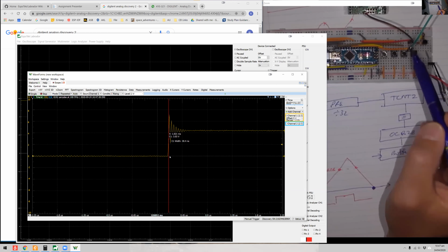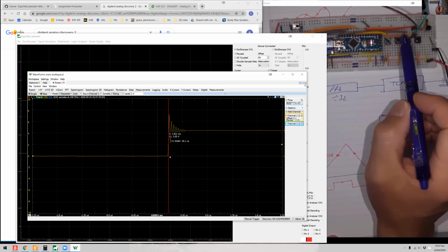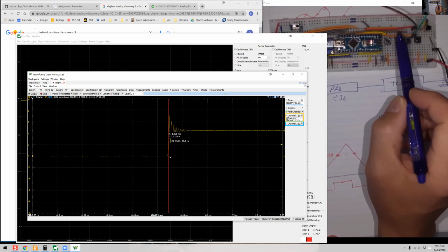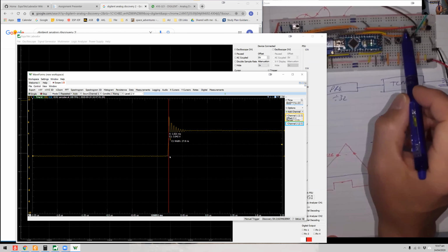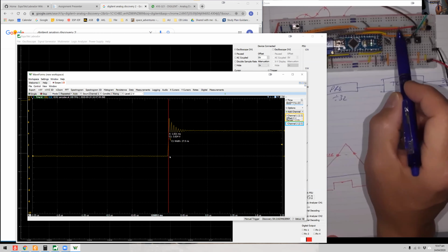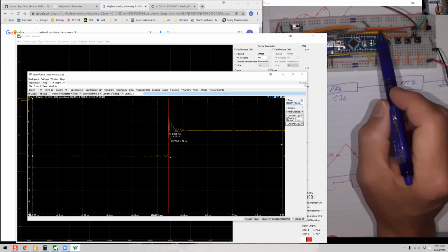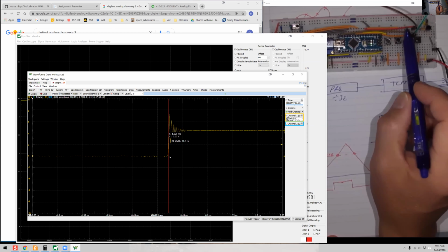Now, effectively what we've got here is an oscillator made up of inductors and capacitors. The reason we've got this inductance and capacitance is because we've got all these wires hanging around in a circuit board. So this is not just a wire, but actually an inductor and a resistor.